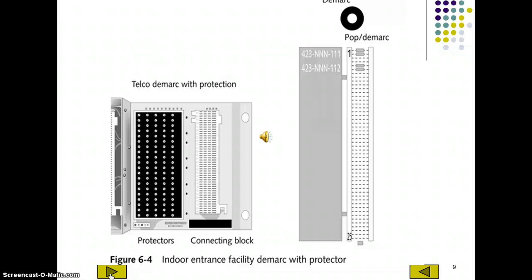First thing that comes to mind is like a T1 circuit, which is a 1.544 megabit bit stream system that has 24 channels concurrently running over it, and it can be voice channels, it can be data channels that can be combined to create a larger data pipe. High cap circuits can be any kind of data service special circuit, and the idea is just to keep your hands off of it and leave it alone. Otherwise you could be disrupting some kind of service. With that, move to the next slide.